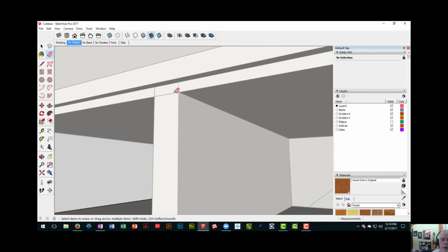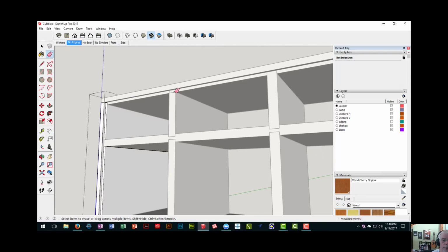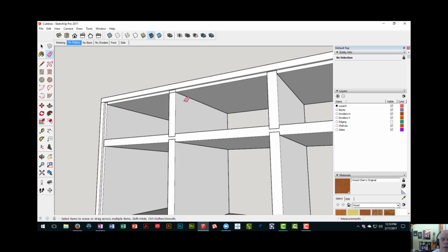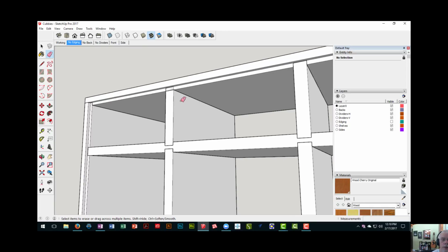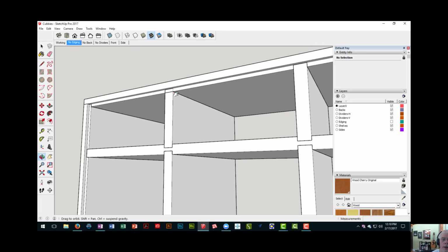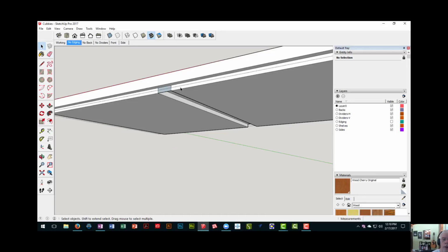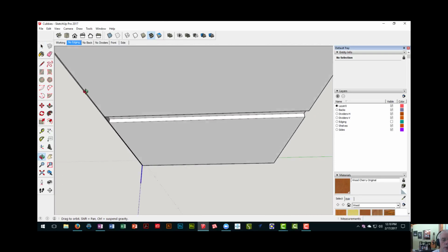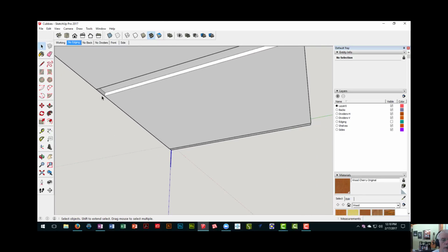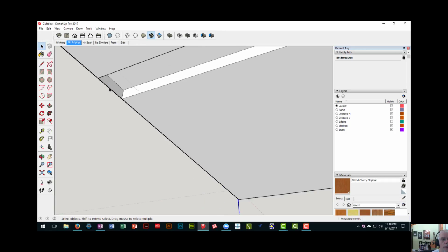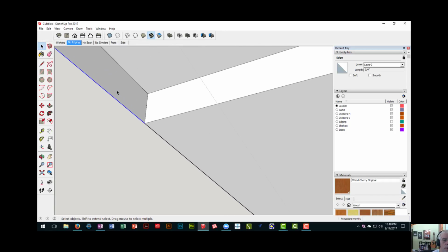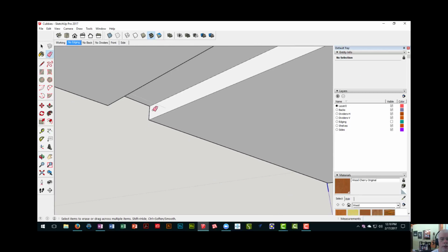And this looks a little funny up here too, so let's check out and see what's going on there. Okay, it looks like there's no dado cut right there for some reason. So I'm going to double click on that and hide the rest of the model. It looks like it got pushed all the way back, but just left a little extra piece. So I'm going to hit E for erase, and I'm just going to erase that extra line, and that fixed that.